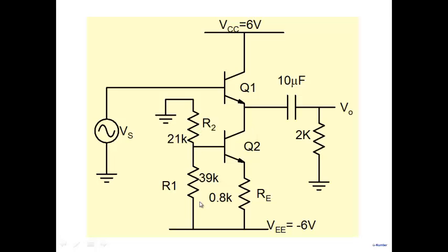You can see this is the familiar biasing circuit with the transistor, and it biases it in the forward active mode and causes a constant current to flow. Why constant current? Because it's in forward active mode and there's no AC signal going into Q2, and therefore it's a constant current source. So this then becomes a better schematic of a common collector amplifier biased through a constant current source.